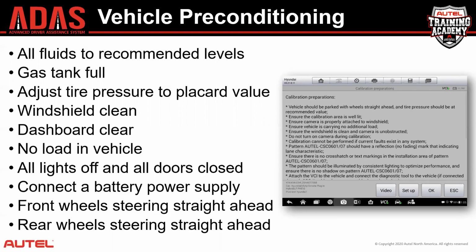It's important that the windshield is clean, especially in front of the camera, that the dashboard is clear, that there's no objects on the dashboard that might reflect in the windshield and again, confuse the camera.